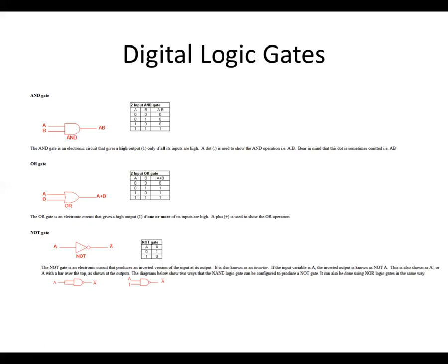NOT is just an inversion. Whatever A is, the output is not A. So if A is 0, then not A is 1. If A is 1, not A is 0. And it's just a device for switching, inverting the logic. So you'll probably see some of those if you look at some schematics.